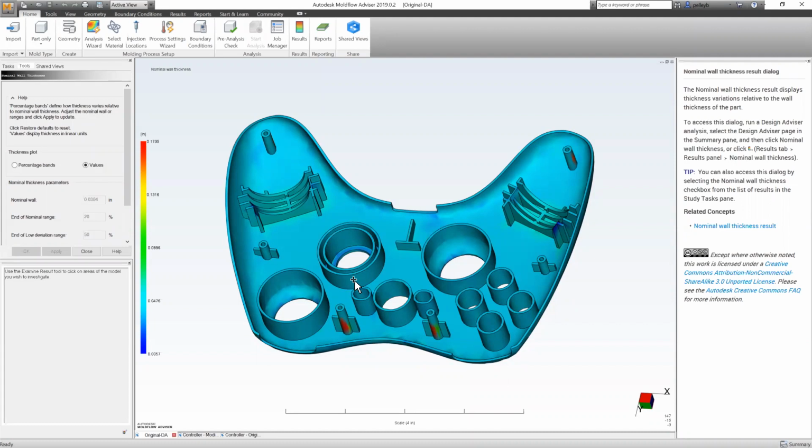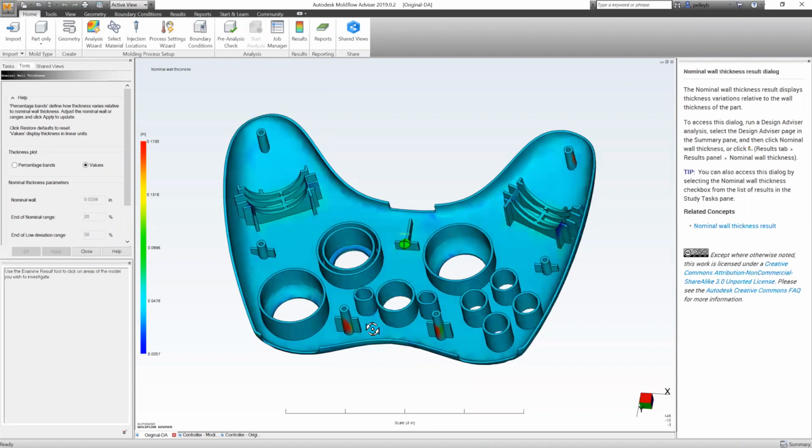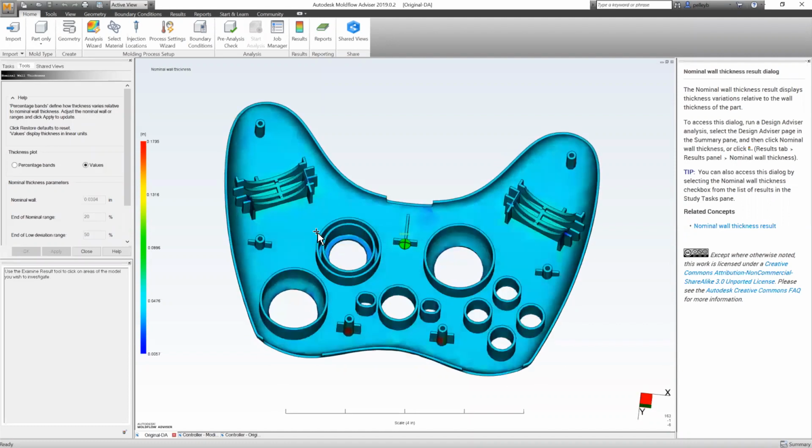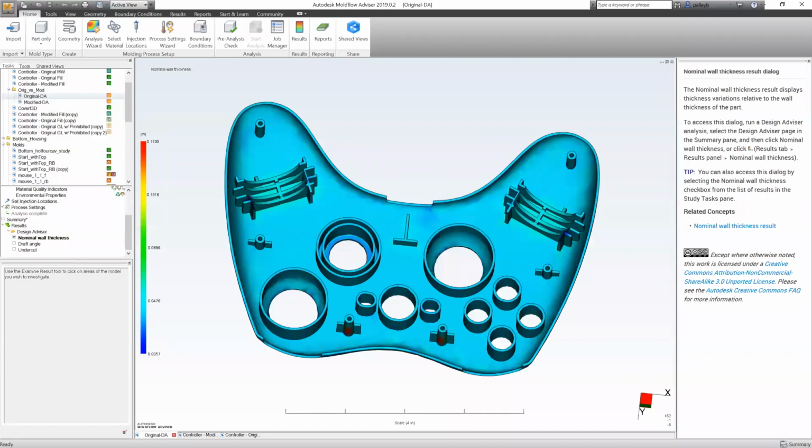As far as internalizing thickness variation: did I core out a boss appropriately? In this case, no. Do I have very thin areas where the flow front's going to pass by and hesitate and perhaps short, or have relatively low shrinkage versus high shrinkage, so blue to red. Not just pretty colors, but stuff that we can internalize and then build upon in regards to what's going to happen next with the next result. Does it correlate to this thickness diagnostic?